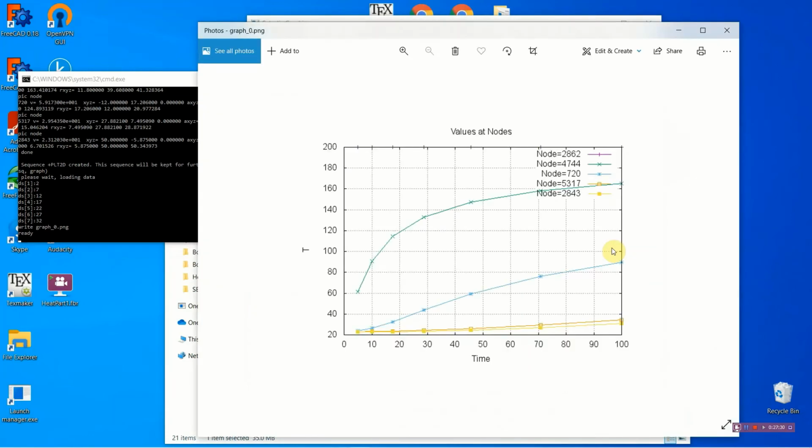and then it will produce this plot of those points from the starting time to the end time, so 100 seconds. There is a line along here which is right at the very beginning of this component, so that's at our 200 degrees. And then the next node I selected is increasing. Well, 23 degrees would be down here, but it's increasing up to just over 160 degrees.